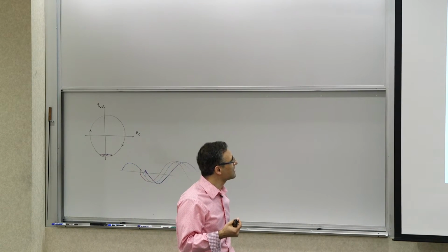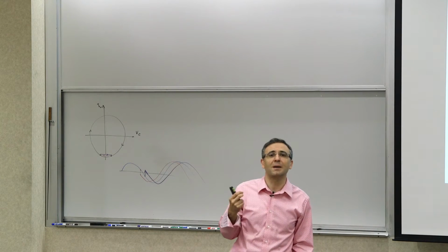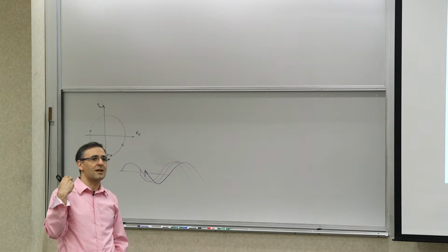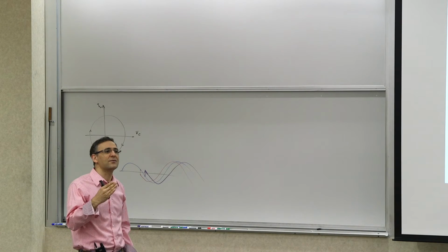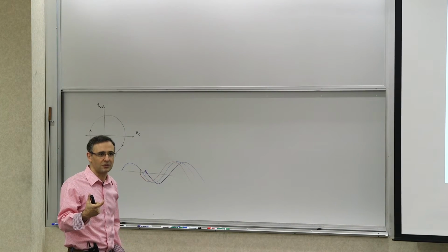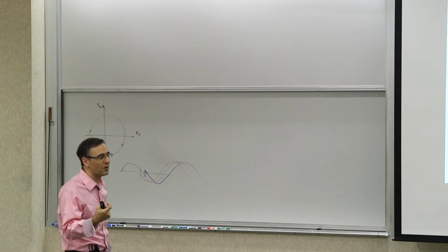So what is the message of this? Since there's no dependence on n, it means that, to first order, in the 1 over f squared region for white noise upconversion, the number of stages doesn't play a role in phase noise. So you can use a larger or shorter one, and it wouldn't affect it.